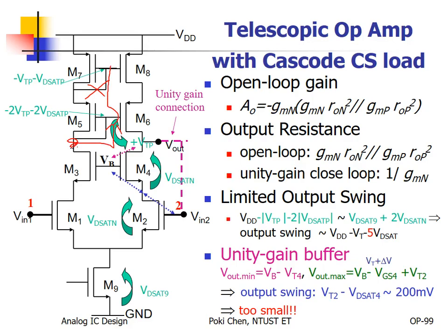Okay? And you need to generate... Nothing is free. You need to generate another bias here. Okay? That's it. Yeah, later I will show you. And how much you can gain? To my memory, only 1 delta V. Not much. Okay, but 1 delta V means maybe again 2 to 3 hundreds of millivolts. Not so bad. Okay, yeah, it almost doubles the output swing, right?